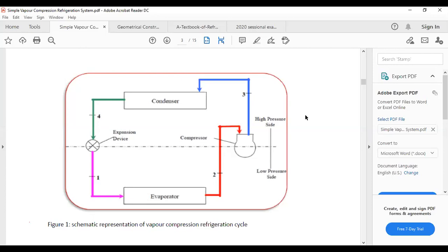So this is high temperature. We release it. But this process of releasing is happening at constant temperature, meaning you are releasing the heat, but the temperature is not changing. That's a pretty part of this system. So the temperature gradient between the atmosphere and the condenser is still the same, and it will release more heat without being compromised. So this gas will change now into a very hot liquid, because the temperature is still high. And then this liquid will go into an expansion device.